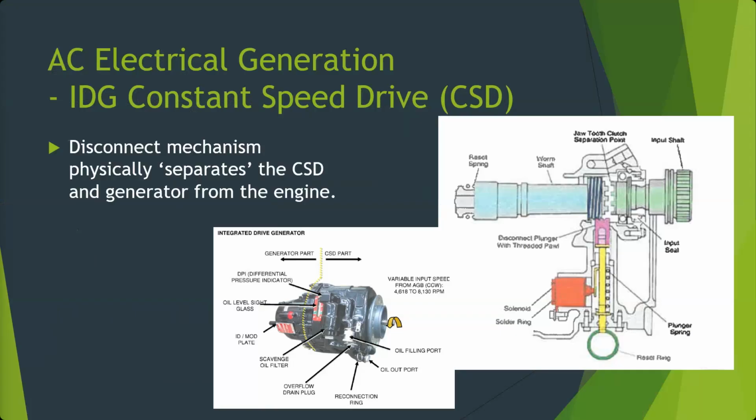And so now you've physically disconnected. So this part right here will continue to spin with the engine. You can see there's not much there that can bind up the engine. And we've disconnected any hydromechanical unit, any reducing gears, and then the generator that's downstream, by separating those.